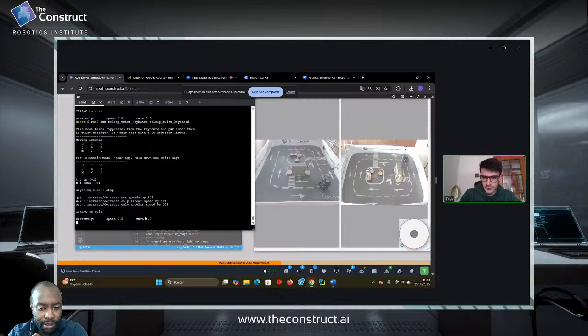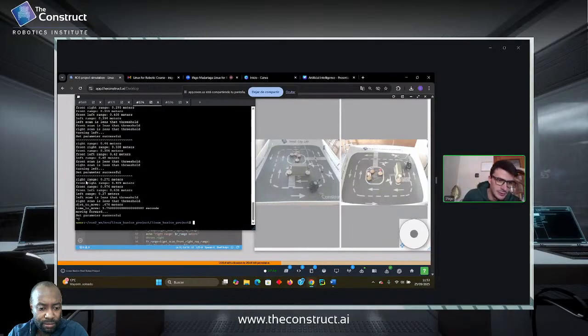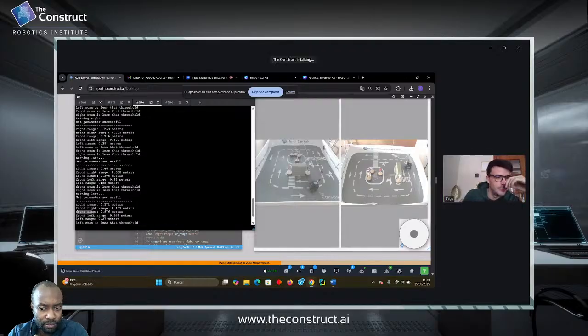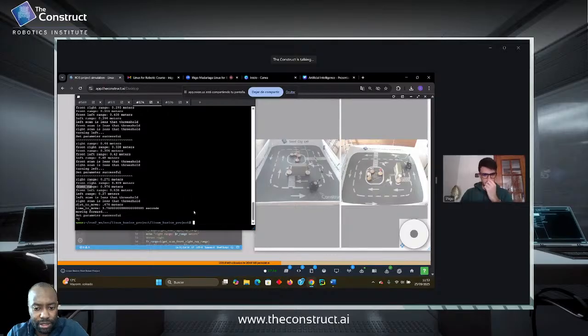Okay. Let me try. And you were speaking about using a threshold value of 0.5. Did you try 0.3 and it didn't work? I changed it to 0.3 because when I was looking at this terminal, it says the front right range, the front is set like all the distance. At the beginning, every range, the front one was really close, lower than 0.5, so that's why the robot was starting to turn around itself. Okay, all right. So let's see how it works right now, because I think the front is quite clear.